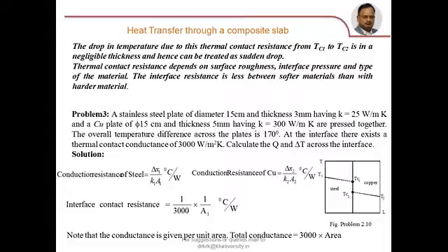So if that copper bottom is not properly attached to the base of the vessel, there exists a void space which will be occupied by the air and offers more resistance for heat transfer, and hence the overall resistance will increase.